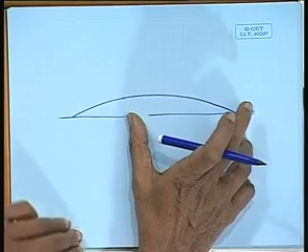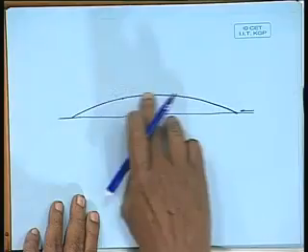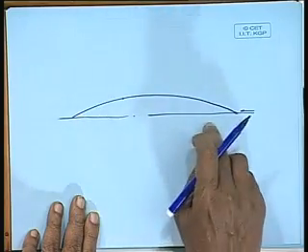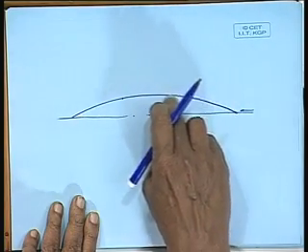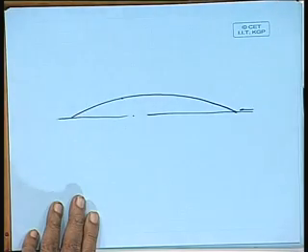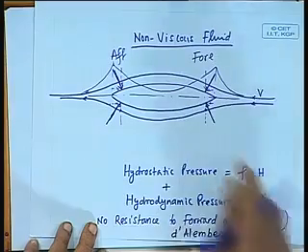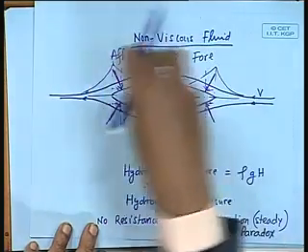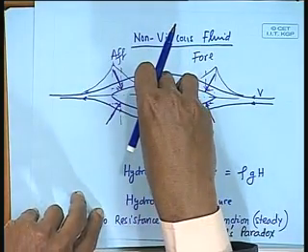This gives you the concept of boundary layer. Am I clear? Okay, let me put it another way. There is a friction between the body and fluid on this surface. So, we have said that velocity on this surface of each particle in contact with it is 0. But previously we have said that the velocity is low here, high here, low here. Pressure is high here, high here, low here.